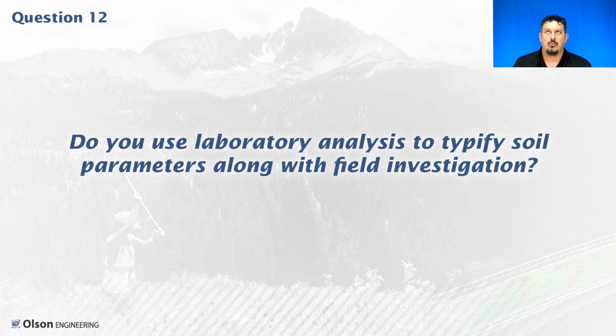So we end up having to make a lot of measurements over a range of moisture contents, a range of compactions, and a range of sample volumes, because there's an entire field of mixing theory, effective medium theory, which asks: if I have an isotropic homogeneous medium and then I start adding materials to it, at different spatial geometries and different sizes, how is that going to affect the bulk measurements?